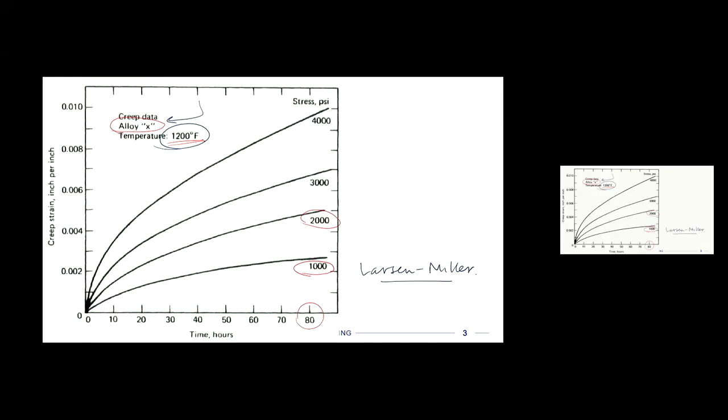Or you can find complementary data that's at different temperatures but the same stress level. And you can see how much each one of those contributes to this Larson-Miller parameter, because all it is is a multiplication of two terms. One is temperature plus a constant, the other one is log of time plus a constant, right? So you can think about the product of those two, and which one is driving the process more. And then make that your reigning understanding of that material and which approach to use. So, yep, unfortunately I do not have more insight than that.